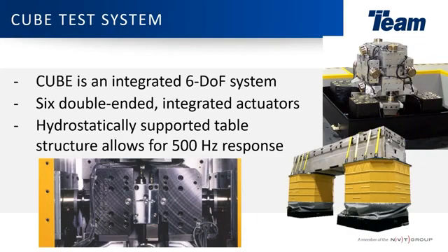So by doing that, if you're moving the cube box in the vertical orientation here, you are actually not adding any weird mechanical connection around the horizontal axes, or actuators rather, while you're exciting it in the vertical orientation. And the benefit of that is you reduce moving weight, and you keep everything symmetrical, nice and happy, and you're able to realize over a 500 hertz frequency response.